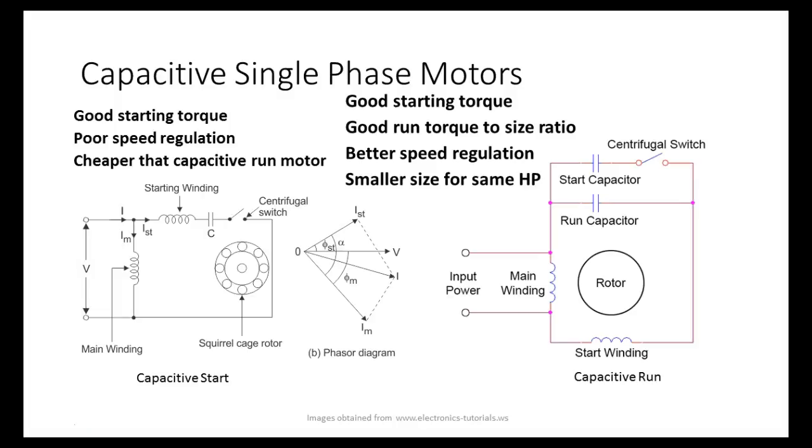So back in motor control, I got a single phase motor and I put L1, L2 in there. The motor ran one way. I swapped them. What did it do? It ran the same direction. Exact same direction. We hooked up a DC motor and I swapped the plus and minus, and it ran in the same direction, because what I was doing is changing the voltage on the field and the armature. Right? You understand it? Which is weird.